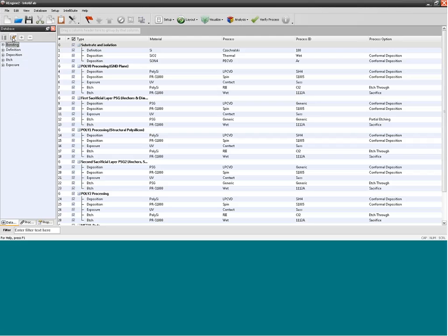To do that, you would simply put this database into the edit mode, and say you had a new material that you want to deposit, you could just add a new material, and it would create this new setting where you could name the material and put in some of the process parameters and properties that you wanted associated with that step. And that's something that's easy to do.